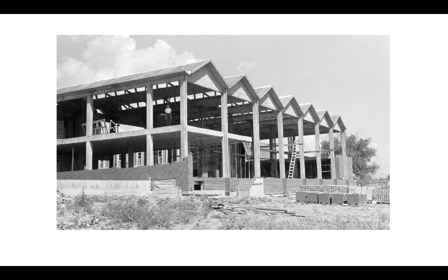A couple of interesting things to note about this structure. You can see right here that edge stiffener beam. That's the thing that's preventing the plate from flattening out, losing its depth, losing its section modulus. And you can see too that where the plate is functioning basically as a web instead of a flange, near the neutral axis, the architects and engineers here have actually sliced out pieces of the folded plate so that they can bring daylight into what's probably a warehouse or a factory building.